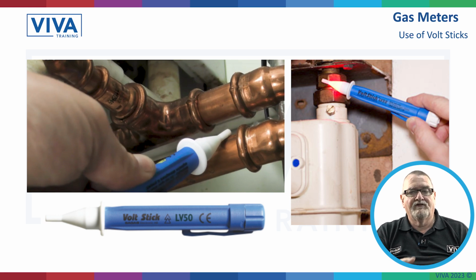these volt sticks, and before they touch the meter or the ECV, they'll put that volt stick on there. They'll test it before they use it, they'll put it onto a known electrical supply, so near a socket, and then it will glow to say that it's illuminated. They'll then put that onto the meter union, onto the pipework, and if it glows, as in the picture there on the side, that's indicating that there's some electricity in that meter, so you wouldn't touch that.